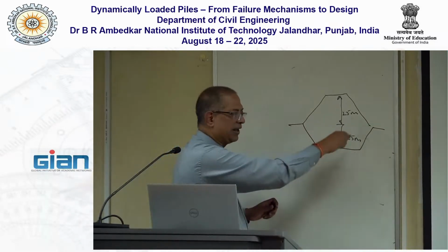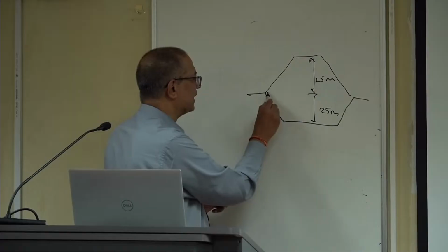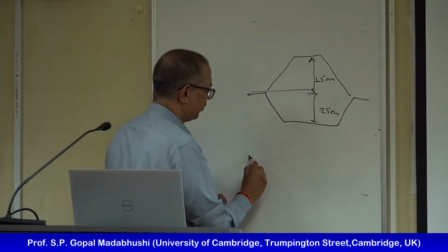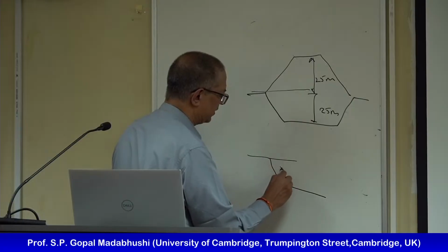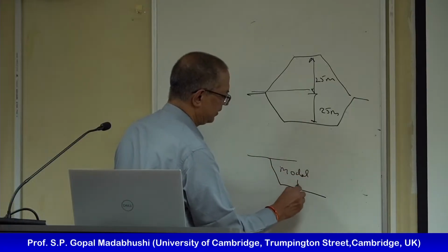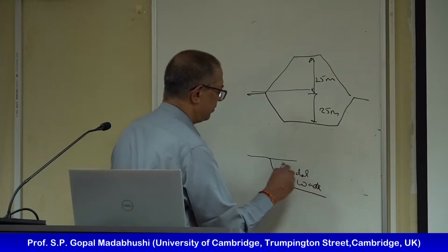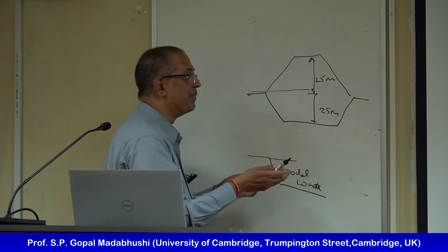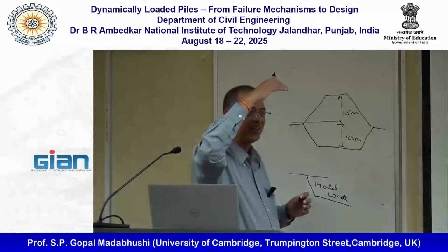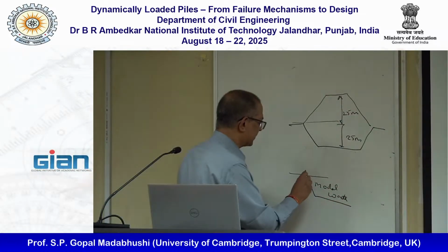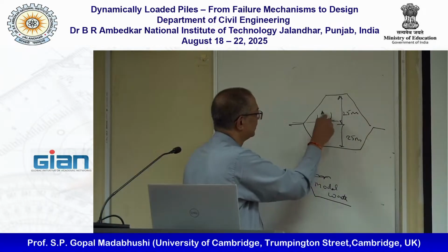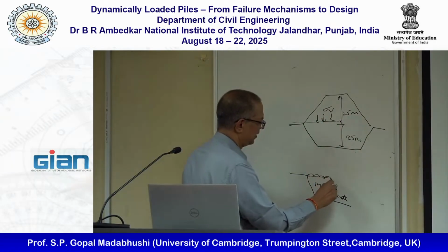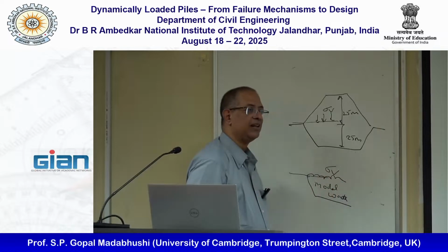We are not modeling all of that. So we are only modeling this bit, right? So what we did was that, okay, we filled the waste till here, but I can't make the model come out of the centrifuge container. So we put surcharge on the top to simulate that stress, using lead shot.